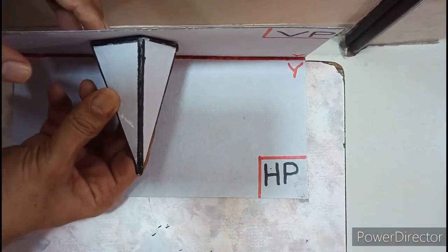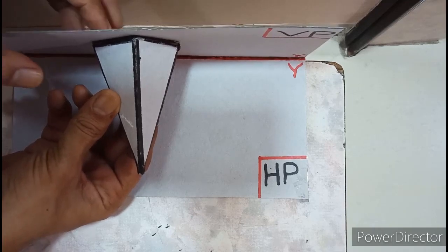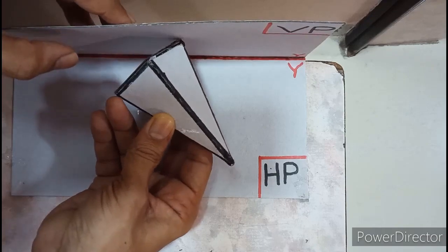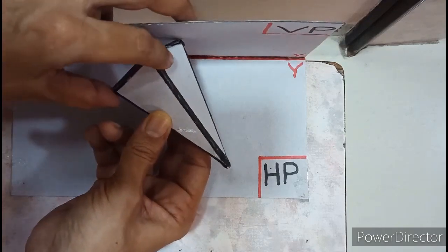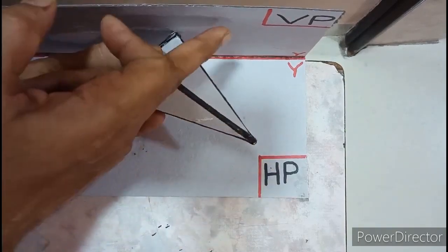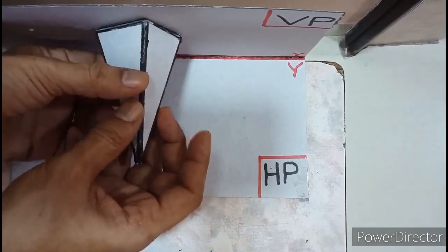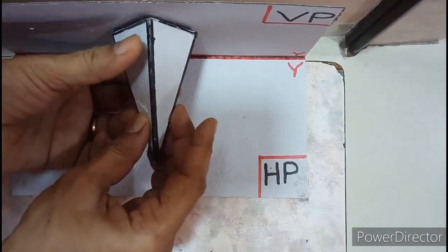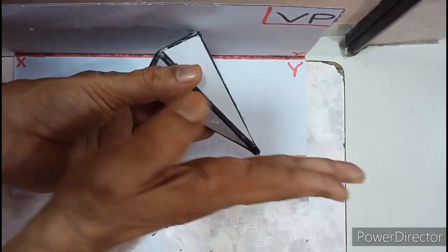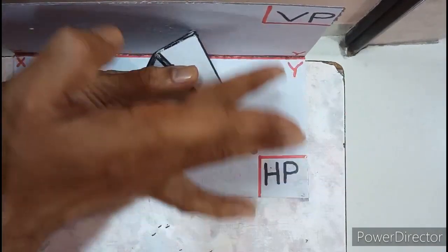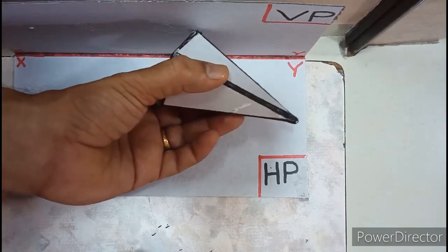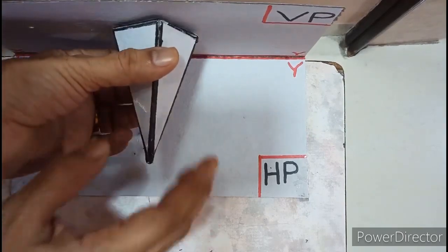That is the question. What you'll be doing is, the right side corner you'll keep on XY and you will tilt the pyramid. Now see this apex, the distance from VP is reduced, because initially this distance was greater, it was 80. The moment you start tilting, one point will remain on VP, and the locus of this apex will be 75 in front. Initially it was 80, now it is 75. See, the moment you tilt, the distance goes on decreasing. So that is the condition, the second stage.